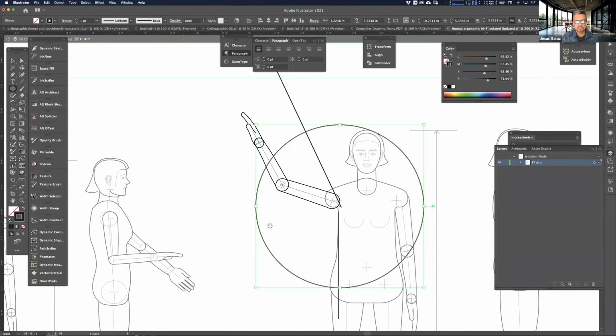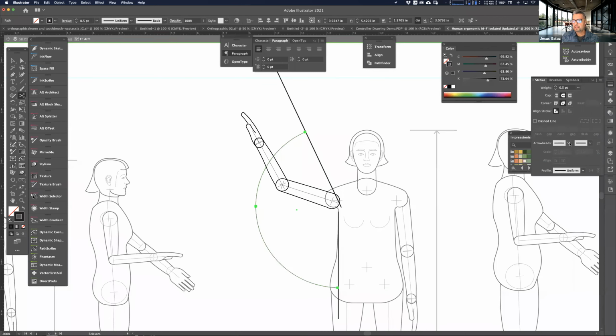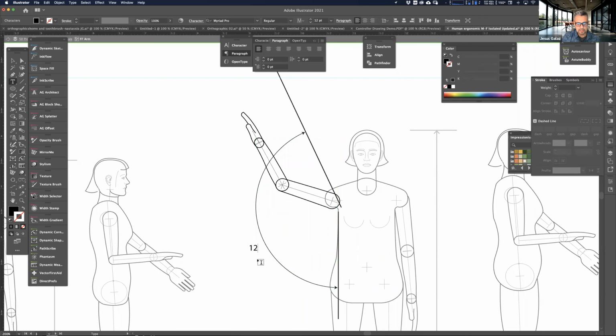where you add that data point there. So something like this, you would cut it in these different parts here, and then add an arrow to it, and put an arrow at the beginning and the end, and then some kind of dimension, right? So let's say it's 128 degrees. And to get the degrees on the Mac, it's Option Shift 8. Shift 8 is the asterisk, Option Shift 8 is the degree symbol. That's how you would get the degree. So maybe you want to do something like that.